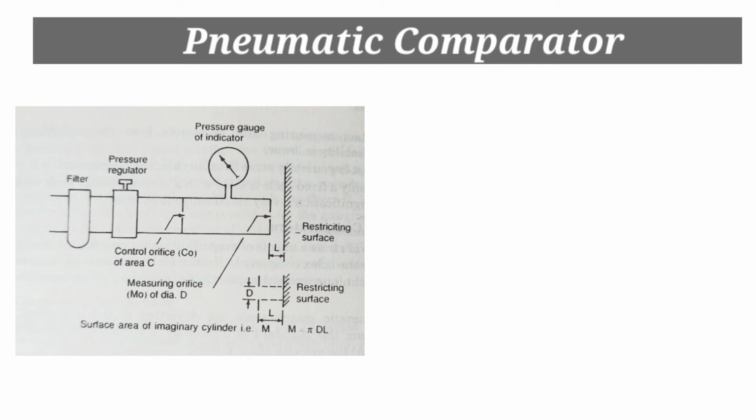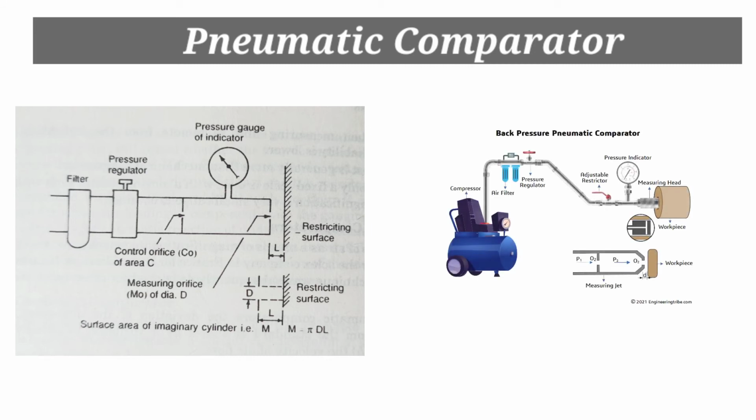The technique offers the advantage of enabling high magnification to be obtained, that is 30 thousand to 1 or more, coupled with good stability and reliability. Such a high order of magnification is possible because no physical contact is made either with the setting gauge or the part being measured, and internal dimensions may be readily measured not only with respect to tolerance boundaries but also with respect to geometric forms.